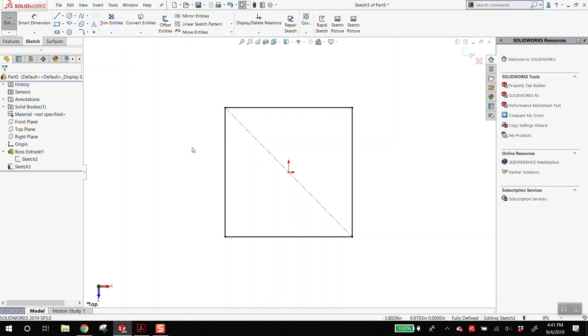Okay. Long answer is, I have a sketch on a piece of paper. I then want to put a sketch on a new piece of paper. And let's say whatever sketch is on here, I want it to be here too. Convert entities is literally just like, take these features and put them here. Does that make sense? Convert entities is useful for working with a master sketch, because the reason that convert entities is more complex than just copy is now if I change sketch 2, because sketch 3 is a convert entities, it will copy whatever changes are made in sketch 2. Does that make sense?